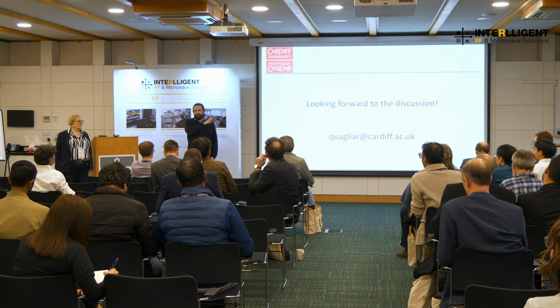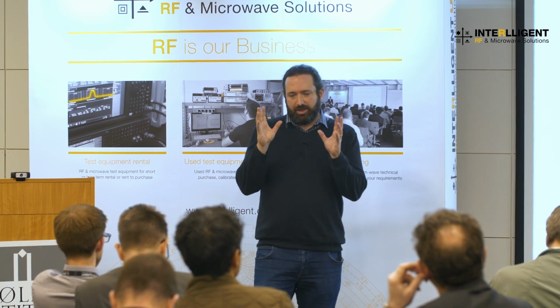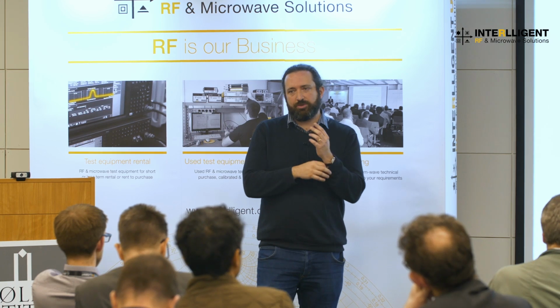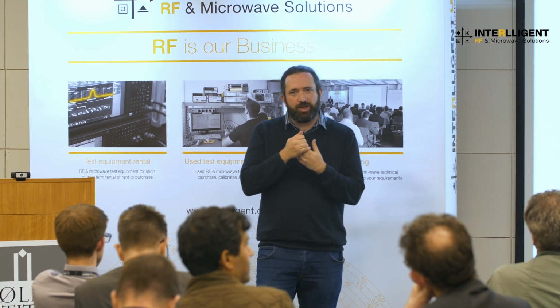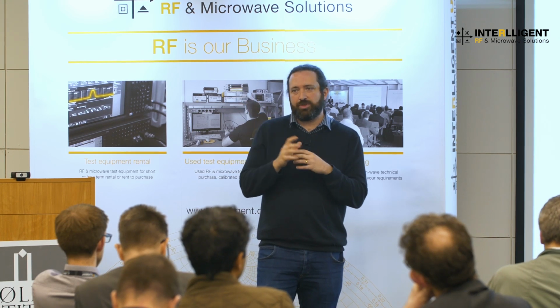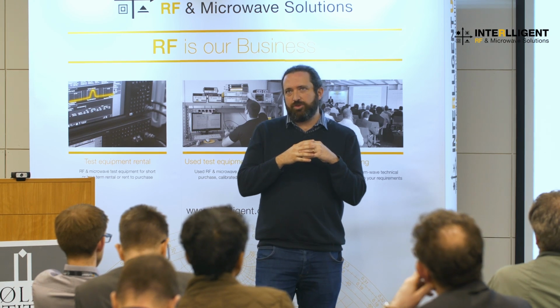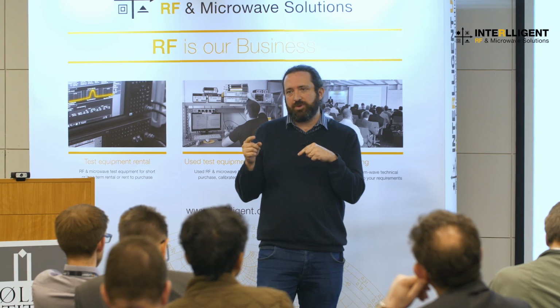they won't capture perfectly this reduction in things. So what you can never expect is to say, oh, I simulate and I know what the bias point will be, because it won't capture that. But they will capture the decrease in power, and normally they're quite good at capturing the position of the optimum. So I think the thing to do is to keep in mind that at the end, you will need to modify that bias point.